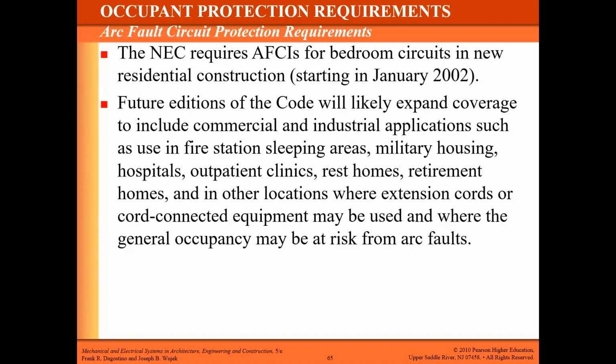It's similar, but it's to prevent the electricity from jumping across to a ground. If there's, for example, a cut in the wire that is undetected, or a screw goes into it during drywall installation, if you get an arc going across, it's just another type of leak, sort of, but it's in an effort to prevent fire from that spark.